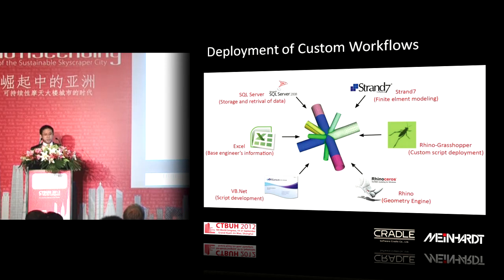As the peer reviewer, we clearly don't have a budget as large as maybe the base engineer, so we needed to automate a lot of our work. You see on the screen all these 6 tools that we've linked together to generate FEA models like that. That clears out a lot of man hours in terms of labor, and allows us engineers to focus on the value-added things, actually verifying that the stresses or the models are generated correctly, as opposed to the manual work of generating everything from geometry to loading to meshing.